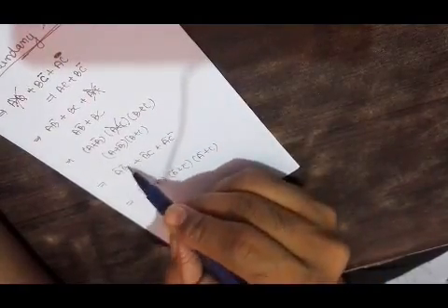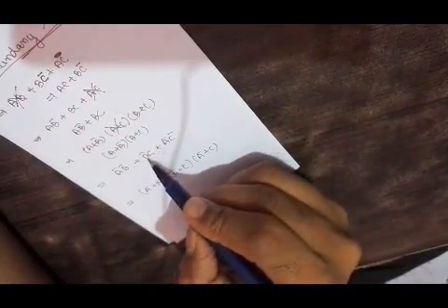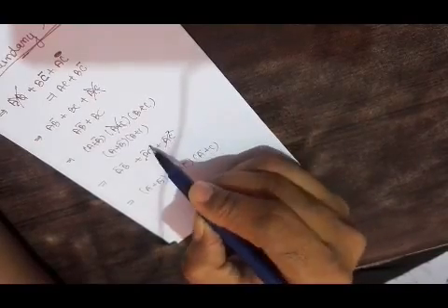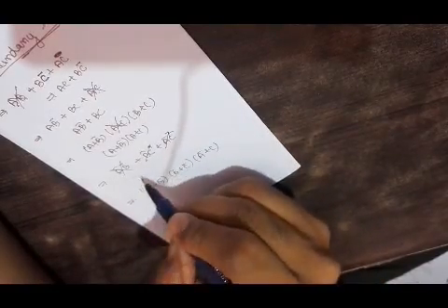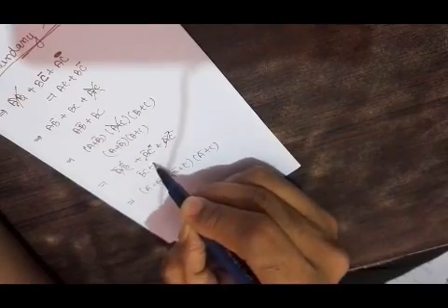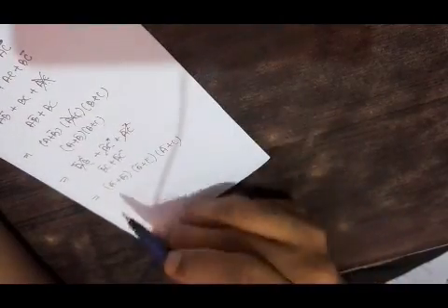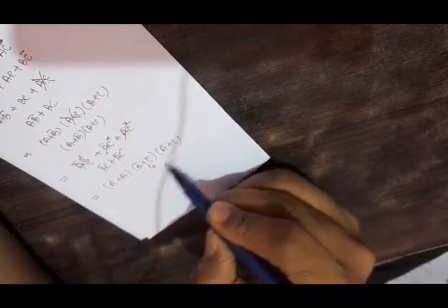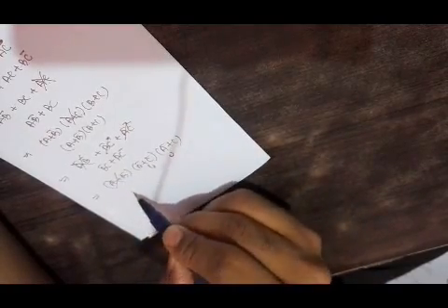Here also this is b bar c, and c is here. We can see that c is going into variations. So these two terms are taken into consideration, and this is a redundancy term: b bar c plus a bar c bar. Finally, here we have bar on all except c, which is going through variations. So these two terms will be considered, and this is redundancy, right?